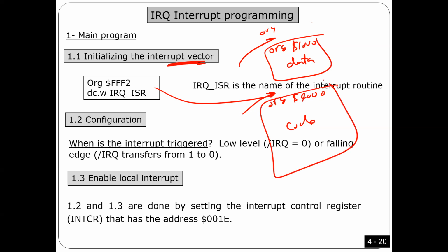So anyway, what I did right now here, guys, is this is the name of the subroutine. You can name it any name, but you have to use the name here, similar to any subroutine. For example, I'm going to call it IRQ underscore ISR colon, then write the subroutine, and then put RTI at the end.